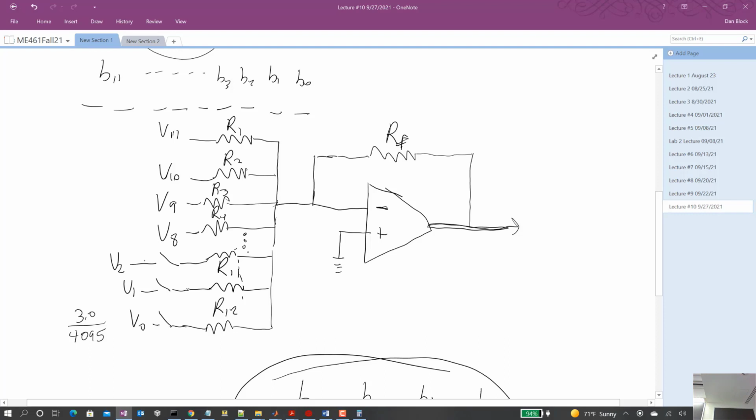So initially every millisecond, we're going to want to go read the voltage that's sitting on our pin. Just the same with the DAC, this output goes to a certain pin on our processor, the 28379D, and then goes out to the world. And we can scope that DAC out. In the same way, there's a pin on our 28379D processor, many pins actually, that can bring in voltage, what we call sample the signal, or figure out what voltage is coming in on that pin. So that's where we have to go next.